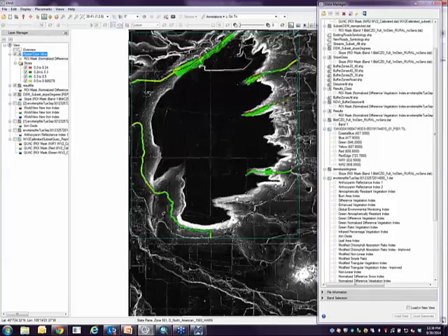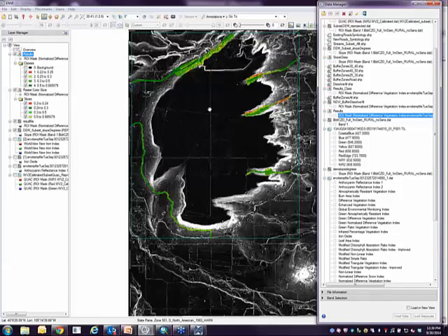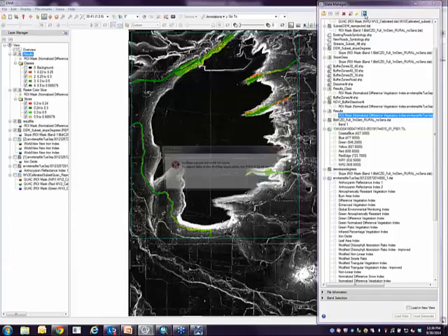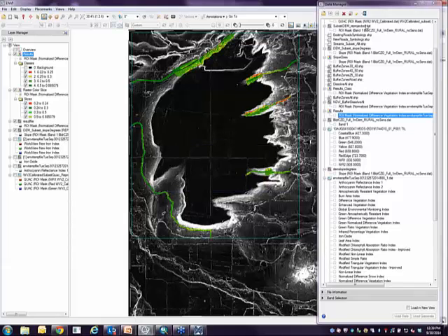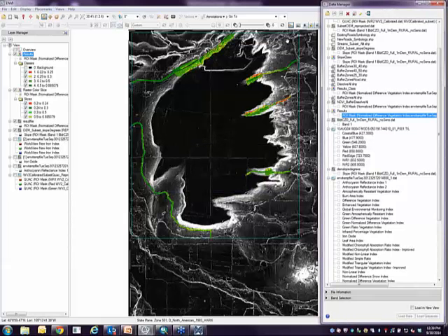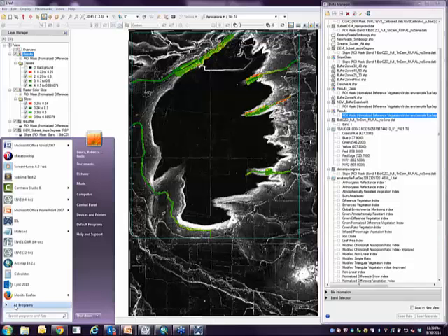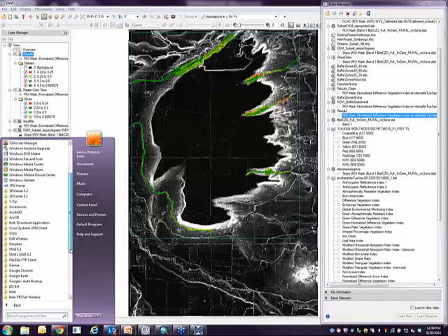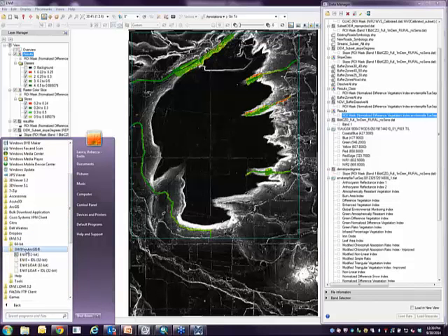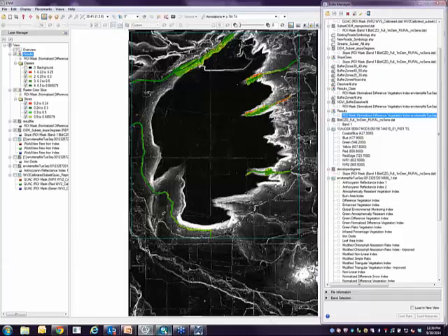Okay, so once this is done and we've got our result, I think I saved my result off here with those other color tables that you saw on the map. Again, I can export this directly to ArcMap, or just add it and then start creating a map. Oh, sorry about that. I'm running ENVI in 64-bit mode, and to have the ArcGIS interoperability, you've got to run in 32-bit. So the ENVI for ArcGIS, I'm just going to show you where that is. When you've got ENVI, you'll have ENVI for ArcGIS, and that's going to be running in 32-bit, so you can use that button. But we did that in advance, and we created our nice map.